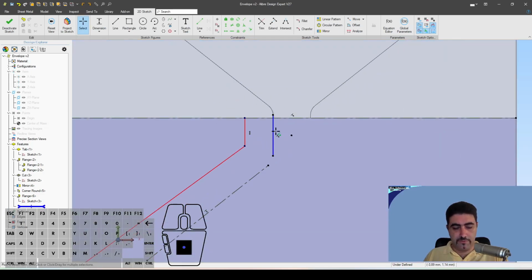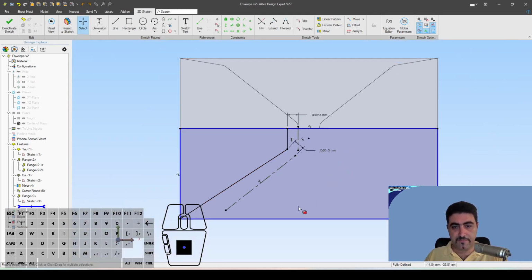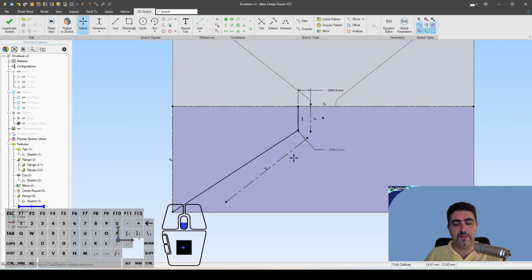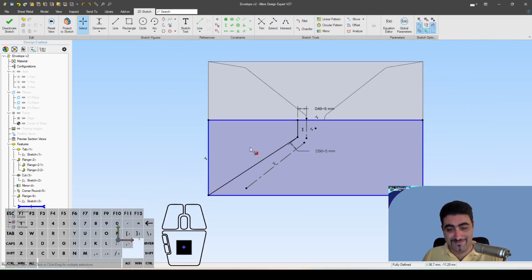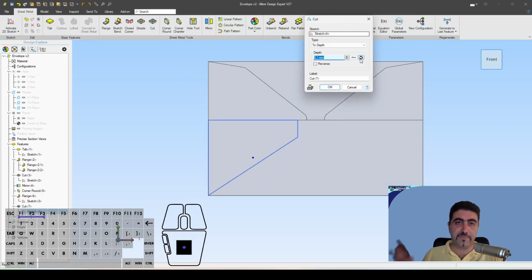So why do I want to have those 5 millimeters at all times? Because I want to have some room, right? Well, it's going to give me at least 5. Sorry. Let's do it this way. Right. Because I want to have some room to put the glue on, right? I might want to glue this, right? Not just fold it. Okay, so that's nice, and I'm going to cut it. Thanks to Nate Liquid Gravity for reminding me that if I click this, it reverts back to the thickness value.